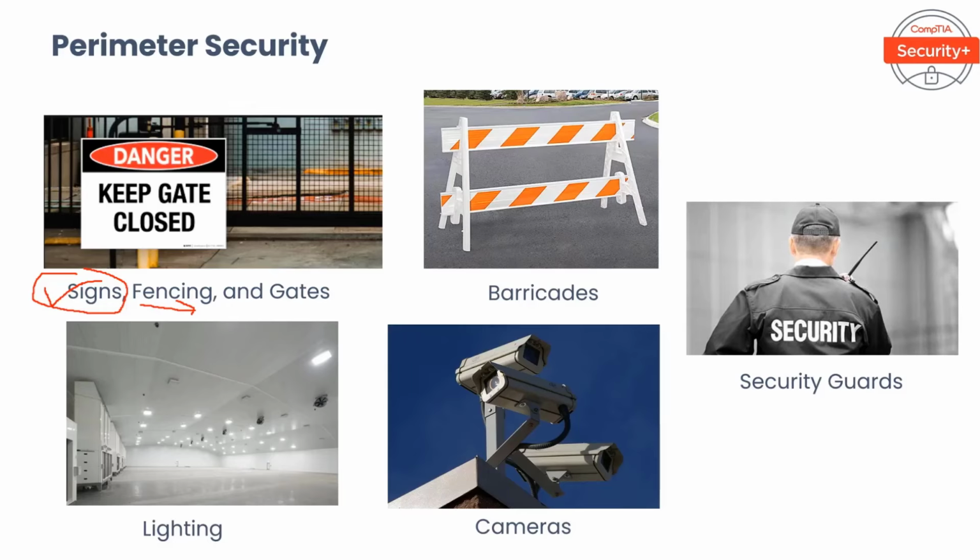One factor to consider in fencing is the height. The higher the fence, the harder it is to get over. To deter intruders, fence height should be 6 or 7 feet. For areas that need to be more secure or to provide protection against a determined intruder, the fence should be 8 feet tall with barbed wire on top.